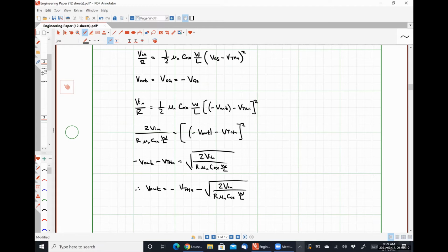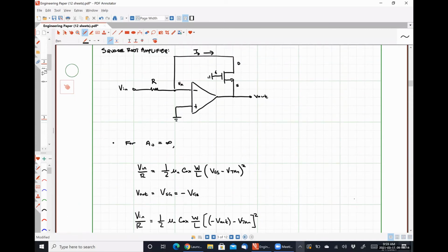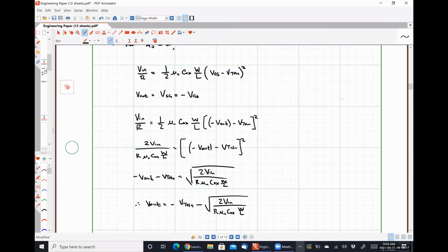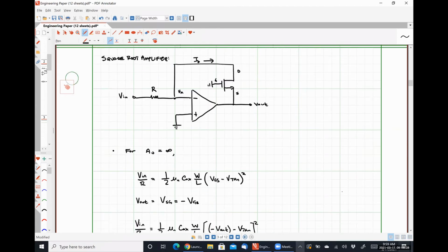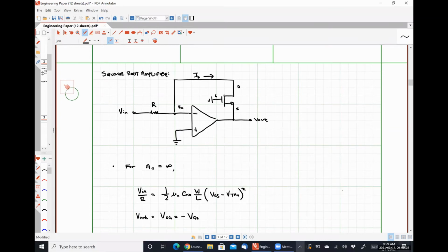Are there any restrictions on our input voltage? Let's look back up here, see if we can figure things out. Or we can look at the mathematical formula. Either way works. So what happens if Vn is negative mathematically? Our output voltage is undefined, right? In the circuit itself, here's where things can maybe get a little bit confusing, right? So a MOSFET transistor is inherently a symmetrical device.